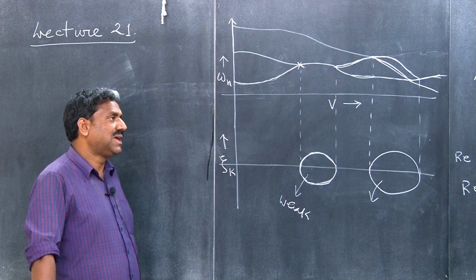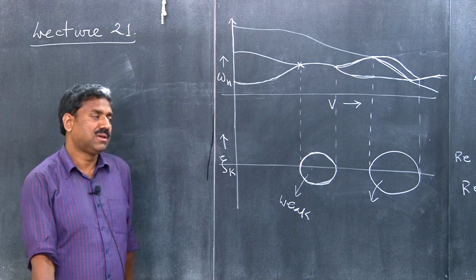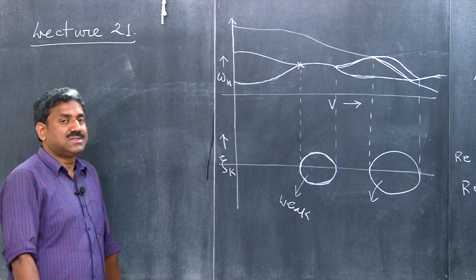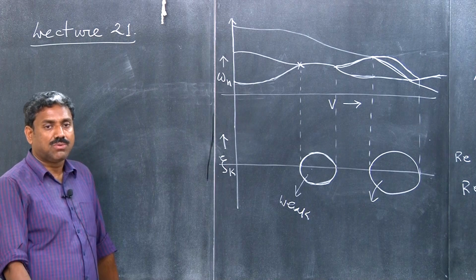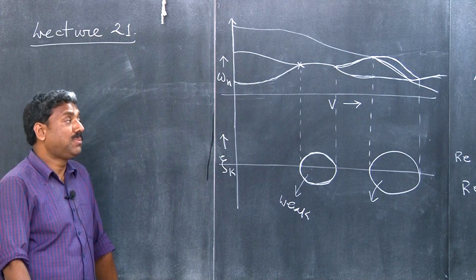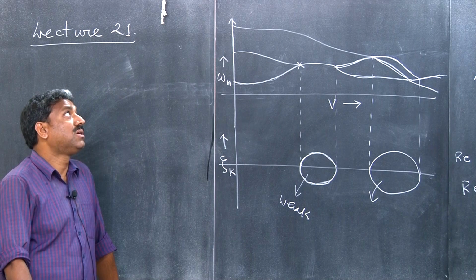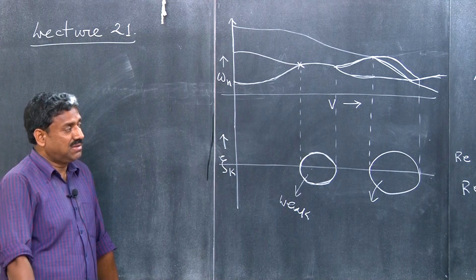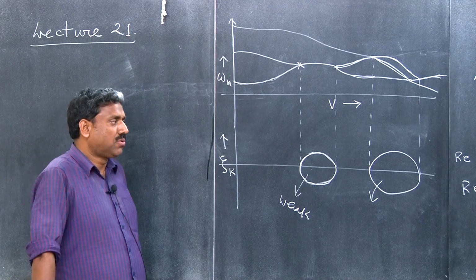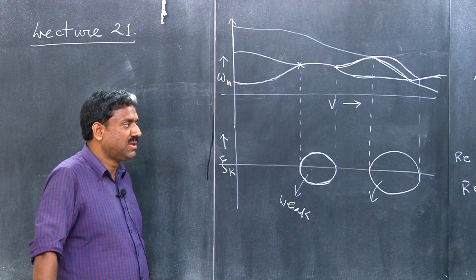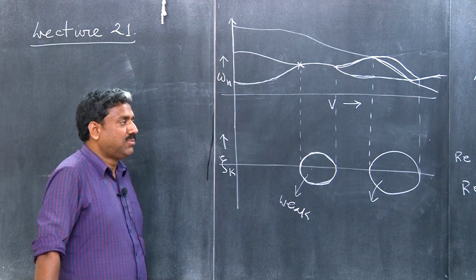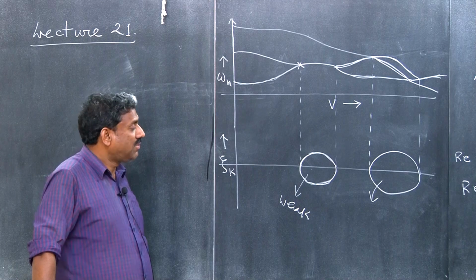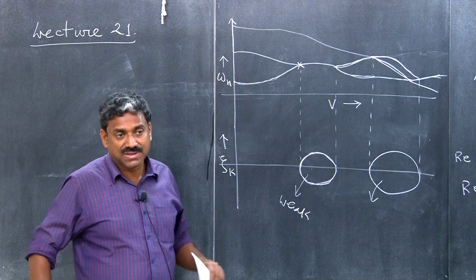So you will see that later, once this aerodynamic, the collapse of Tacoma Bridge, there have been a huge research effort to really understand what was basically going on, okay, and people started understanding the aerodynamic instability. And there are various means to control the flutter, but one of them of course is by putting additional damping or augmenting the system with damping, okay. So the additional damping will suppress this.